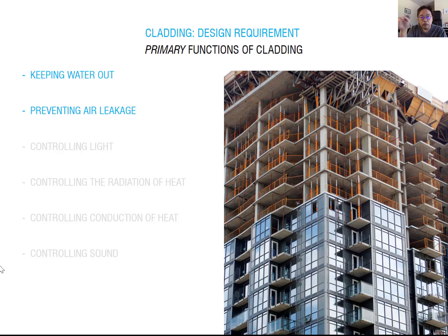Also, you have to understand how to design to prevent air leakage. Prevent unintended passage of air between indoor and outdoor. Air leaks waste conditioned air. So it means you have to be concerned about how you can make air tightness.